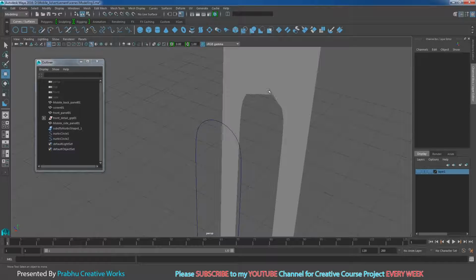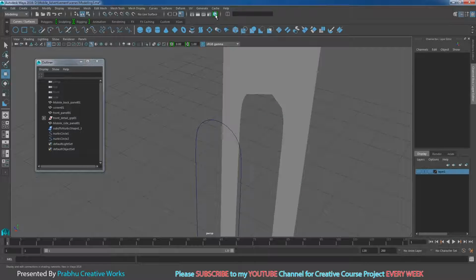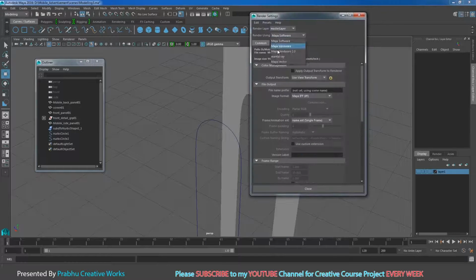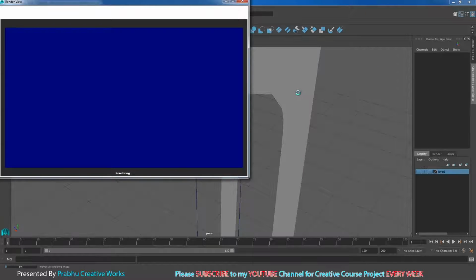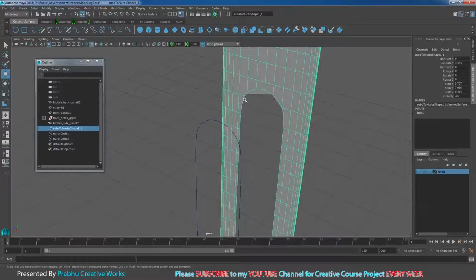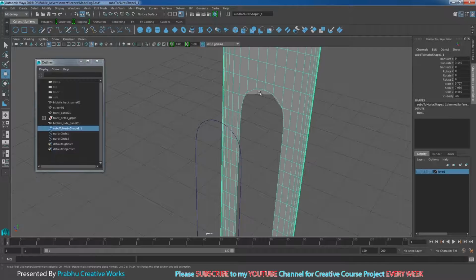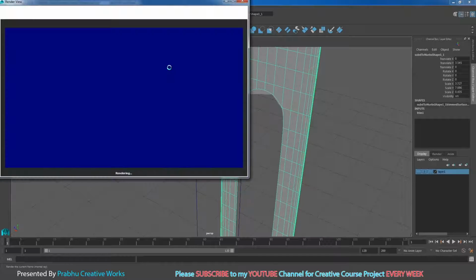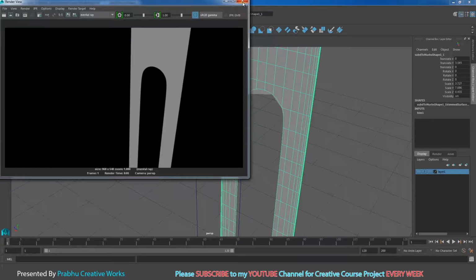Don't bother about this jagginess, because when we render, go to render settings and choose mental ray. When you render, the hole will be clean in mental ray. It will only be shown in render view. In perspective it will look like it has a problem, but in render view we have a clear hole. See here. So that's enough.